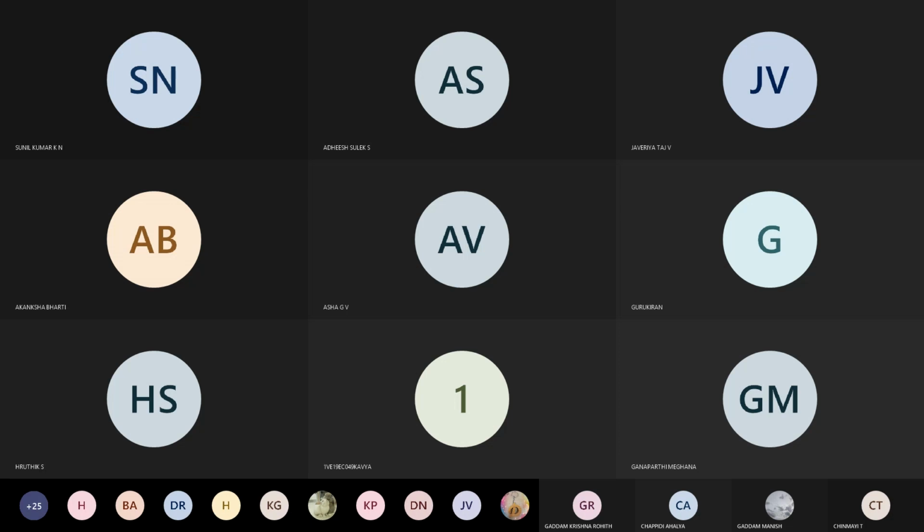Now, V1 will be equal to what? Since you connect equal resistances for each individual source, V1 will be equal to VA by 3 plus VB by 3 plus VC by 3. How you get VA by 3 we will see. Whatever the input voltages VA, VB, VC are, you will get VA by 3, VB by 3 and VC by 3 as the voltage across V1.